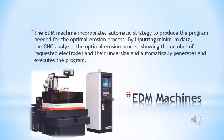Now the EDM machines. The EDM machines incorporate an automatic strategy to produce the program needed for the optimal erosion process. By inputting minimum data, the CNC can analyze the optimal erosion process, showing the number of requested electrodes and the undersize, and it automatically generates and executes the program on itself.